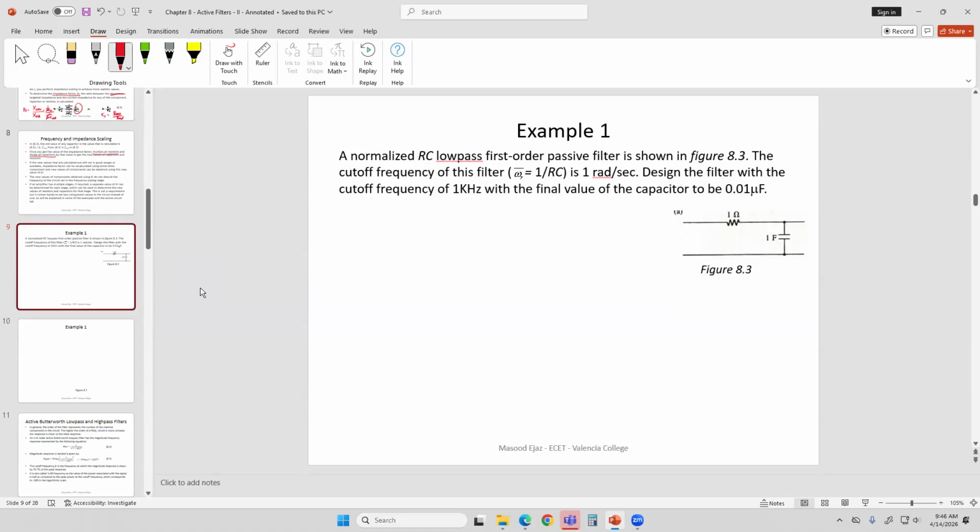So in this case, you can determine if it's a low pass filter or high pass filter based on the reactance of the capacitor. Same thing with the inductor. Instead of a capacitor, if you use an inductor, you can determine at what frequencies the reactance is high and at what frequencies it is low. Based on that, you can determine if the output is going to exist at those frequencies or be 0.